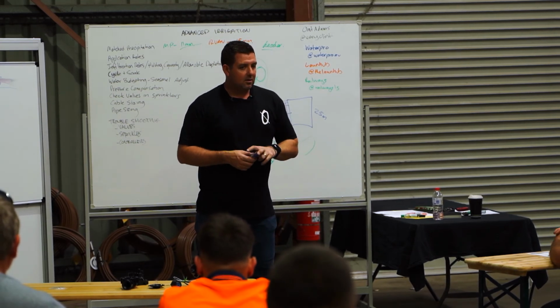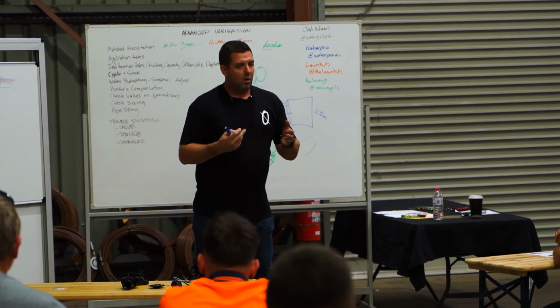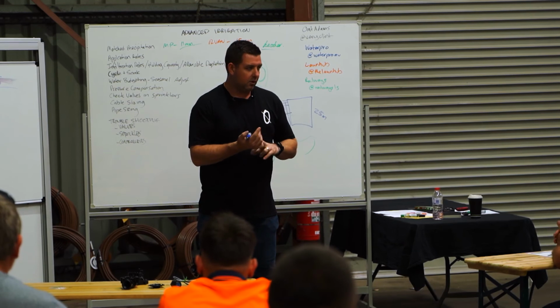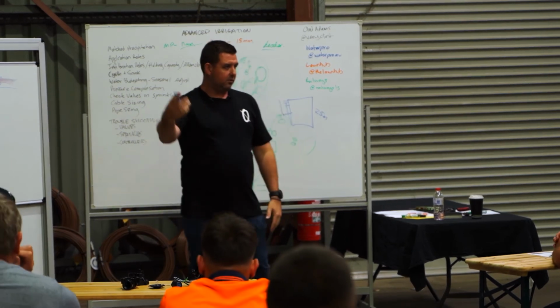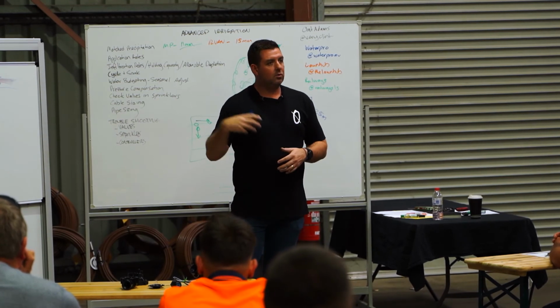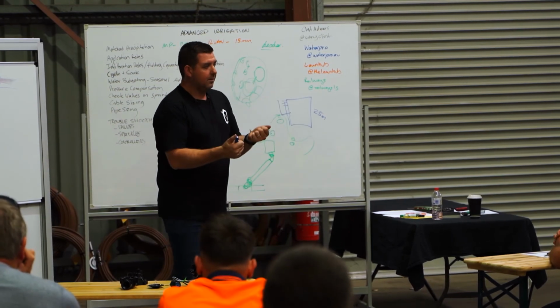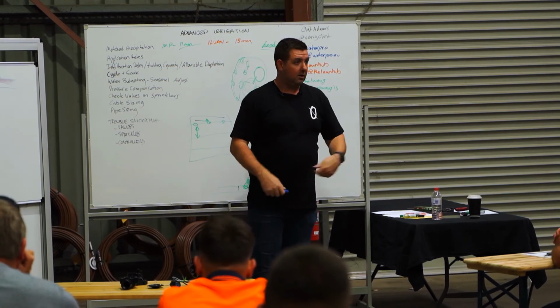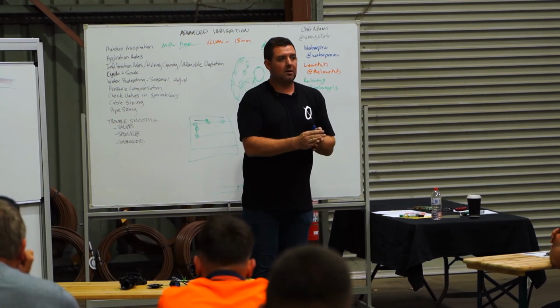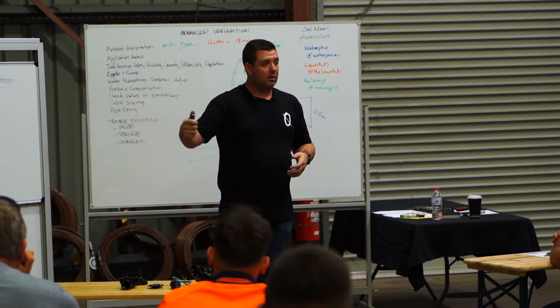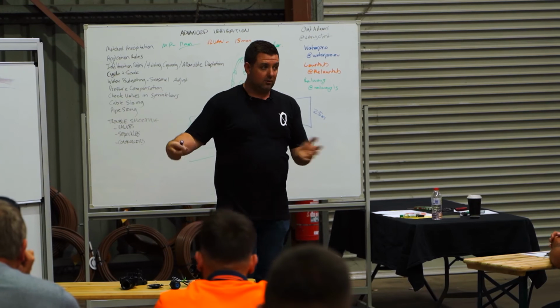Matt yesterday recommended to people that if you're going to put a Wi-Fi controller in your house, obviously the first thing you want to do is make sure that you've got signal where it's going. You can use your phone to see how many bars you're getting out there. You would do a Wi-Fi test now, when you do a water flow test, so that you've got all that ready to go. Program the controller in your house close to your router in a wall and make sure that it's working, so that if you do take it out into a shed and plug it into the wall and it doesn't work, you know that it's not the controller and it's not you. It's just too far away.